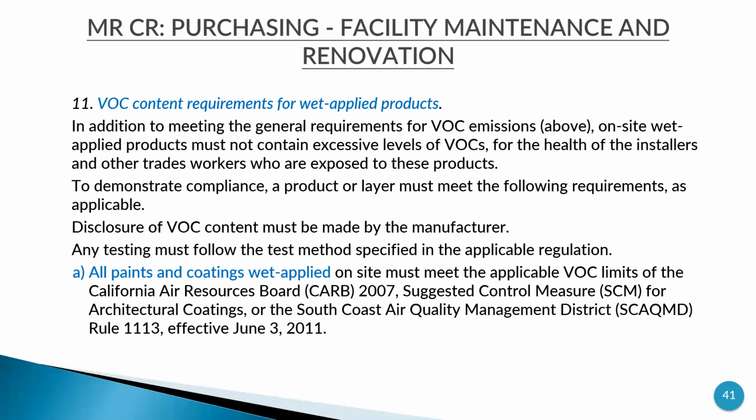While installing, because it comes in pieces, for example for a pipe, it will come in a pipe shape. You just put it on, and on top of it you do the cladding with the sheet, roll the sheet over the top and just rivet it. So in the buildings they do use the insulation for the thermal purpose, chilled water lines and all that.